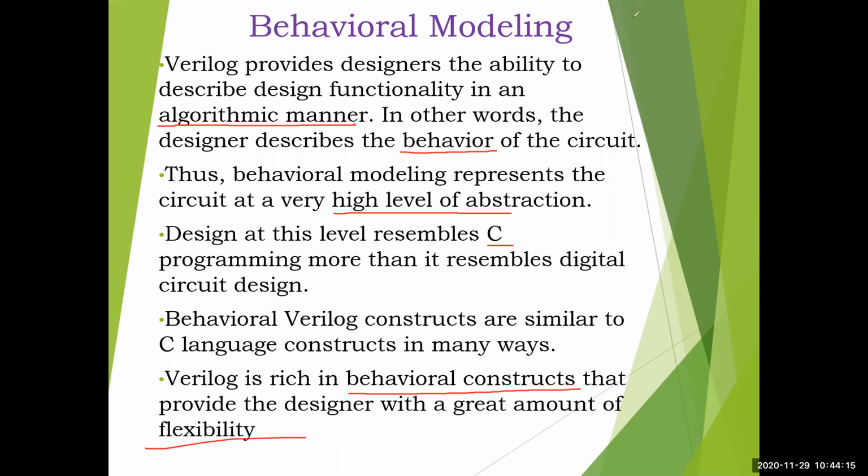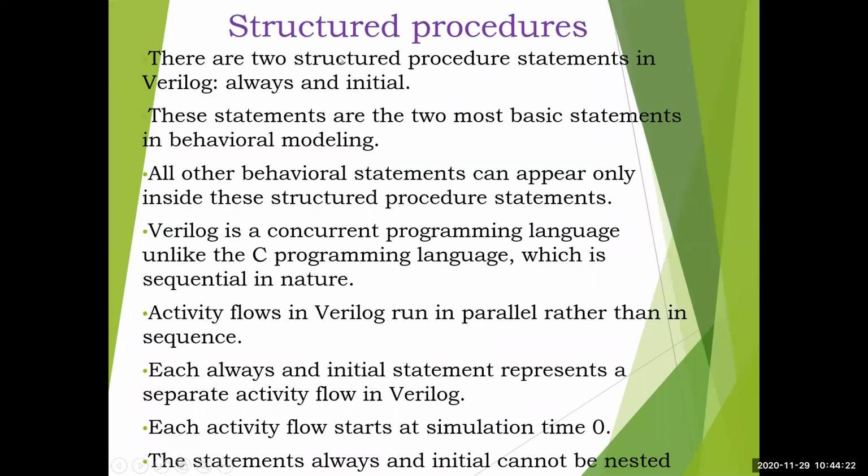Okay, fine. So with this, we will take up the first topic, structured procedures. There are two structured procedure statements in Verilog. One is always and another is initial. The name itself says it: initial means initialization. So it will be used only once in the program. Normally it is used in a stimulus block most of the time, or in a counter case. If you have to initialize the counter value to start from 0 or something, we will use this keyword.